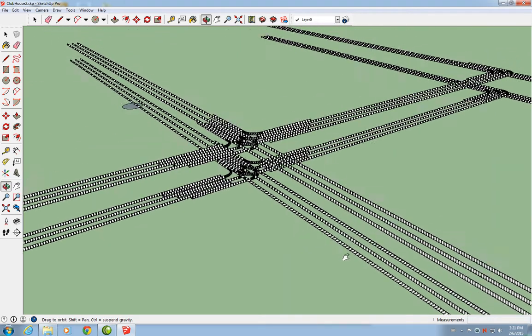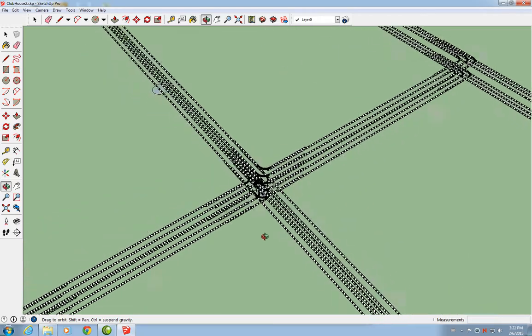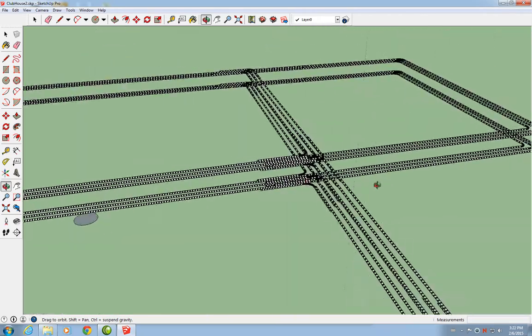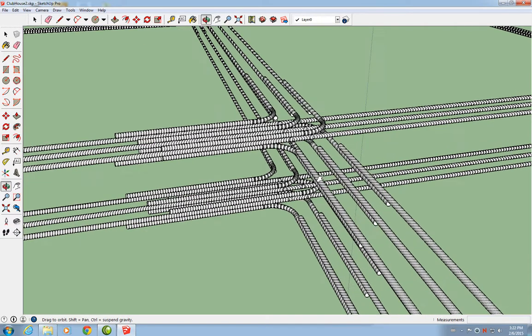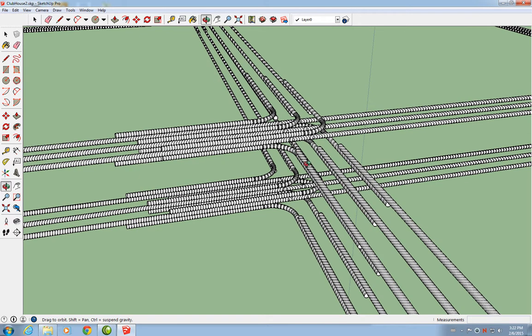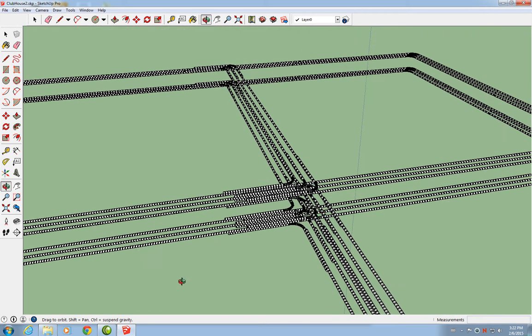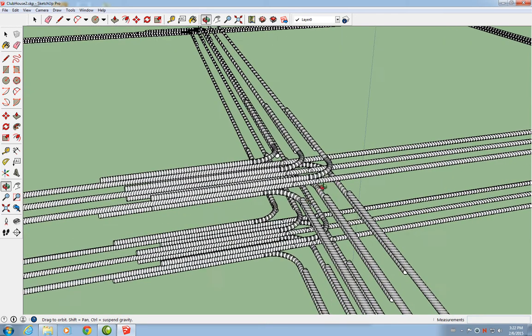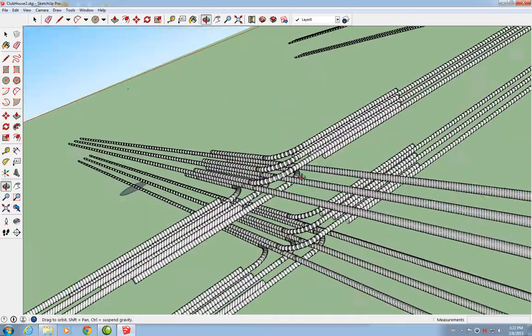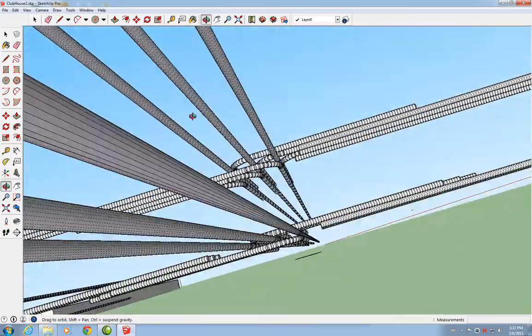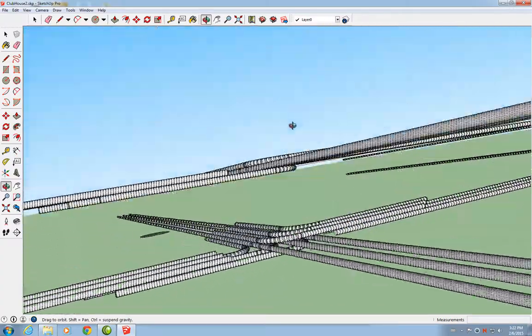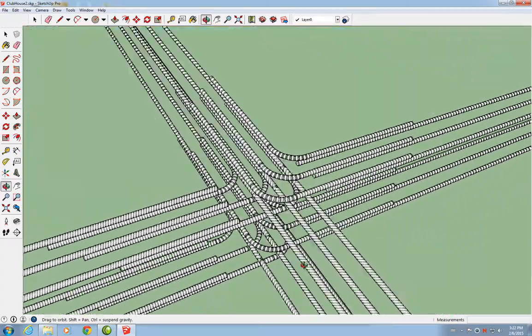Now, in some places we have corners. So in those corners we have intersection. The straight bar that comes from one side is connected to the straight bar that goes to another one by a bar that is 90 degrees with 30 inches on each side. That information can be found in the drawings. So you can look at the drawings, and this is about how they will look like in those intersections.